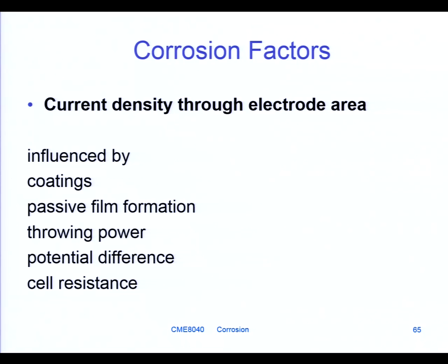And that's one of the reasons why when you go into closed loop systems, into power station systems, they tend to use low conductivity water with a high resistance. So that reduces the amount of corrosion current. So, although the Faraday's law calculation just looks at current flow, total current flow through the anode, really in terms of loss of through section thickness, you begin to start thinking about current density instead.